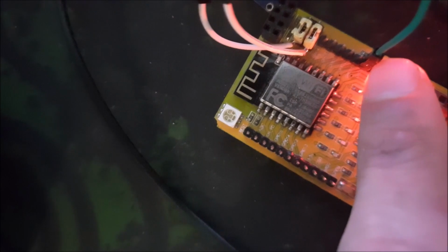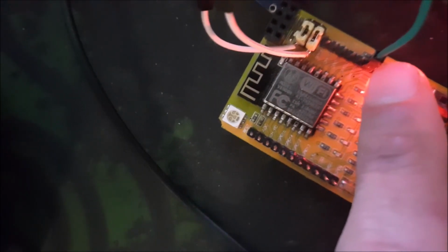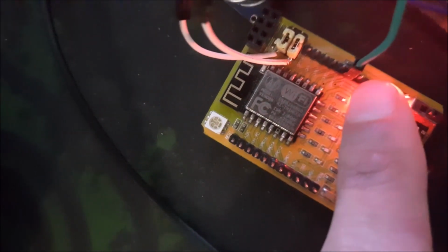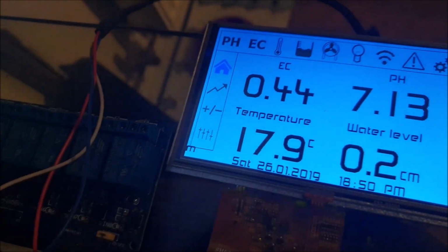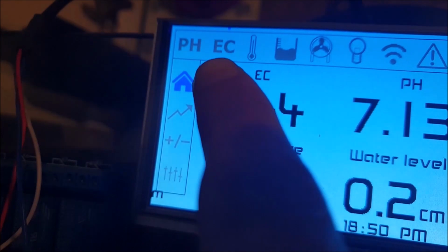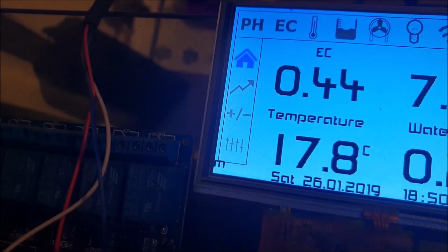That's all the pins jumped out there. The LED will flash each time it gets a packet back from the server saying that it's got a successful response. So that's quite useful. And of course, that response is then sent over serial to the Mega, where the Mega then knows that it's connected. And I'm going to add a little Wi-Fi LED in the corner to display the status.